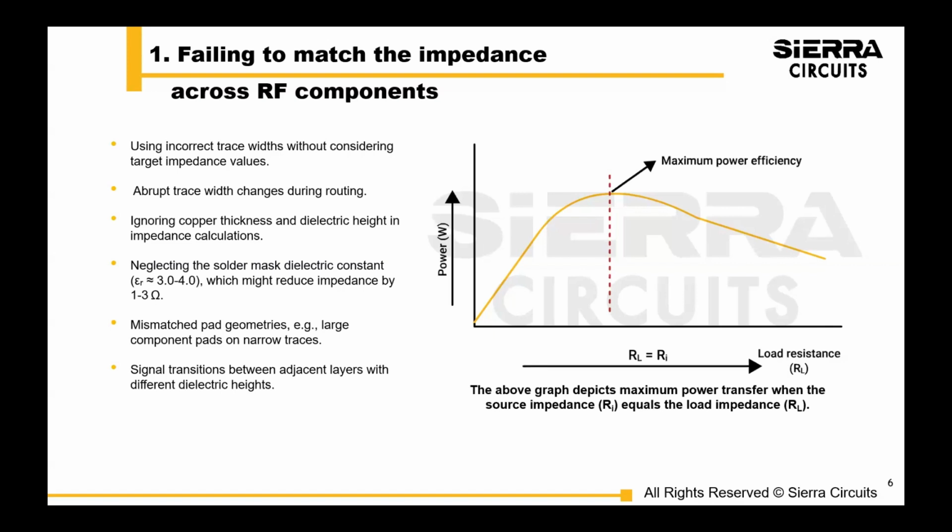That's an easy consideration. Knowing what your solder mask thickness is post manufacturing, I think is a nice little nugget. So if you get a cross section of your board after manufacturing, you can understand your model a little bit better.